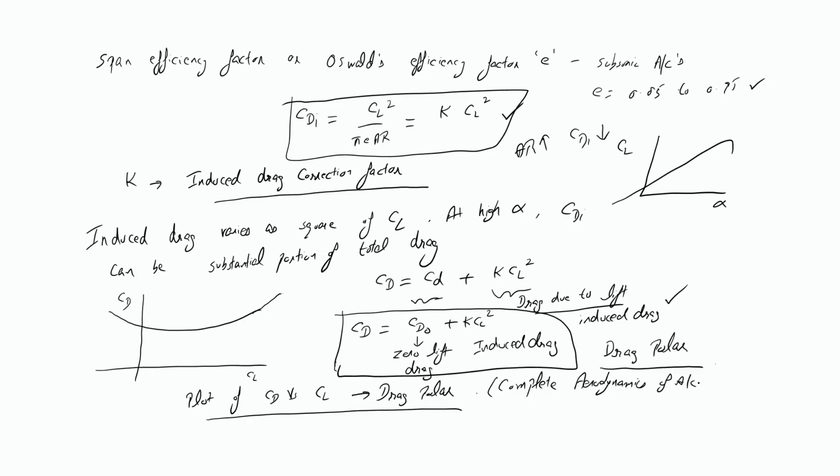So whenever any company, for example airline companies, procure or lease aircraft from the aircraft manufacturers, in the technical details the drag polar will always be mentioned. What is CD naught? What is K? Okay, so this is the basic equation, that is the drag polar equation. Okay. Now we have considered this for a 3D wing, that is the finite wing, where the tips of the wings exist.